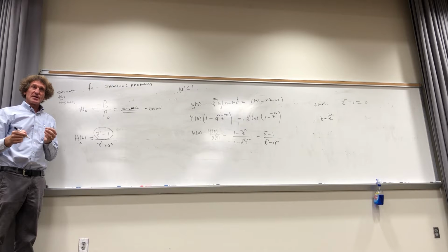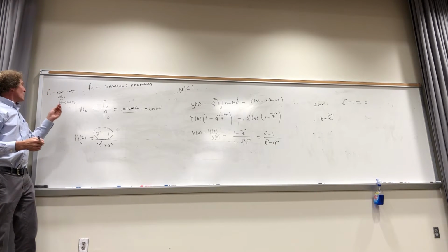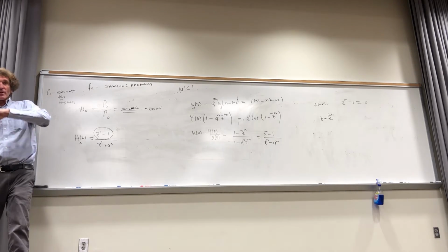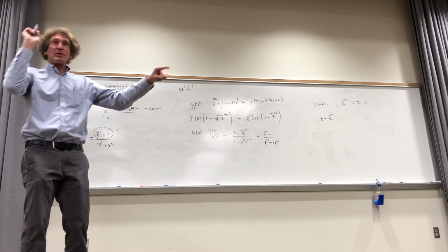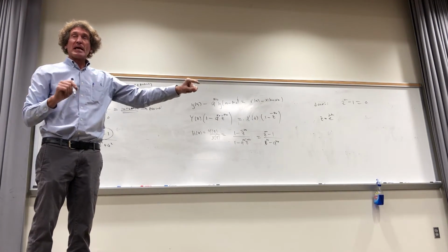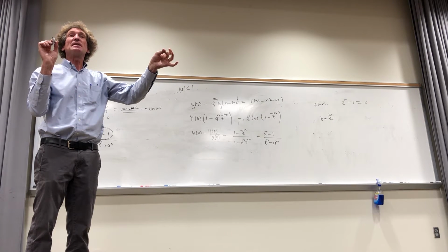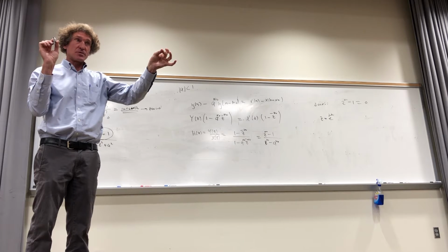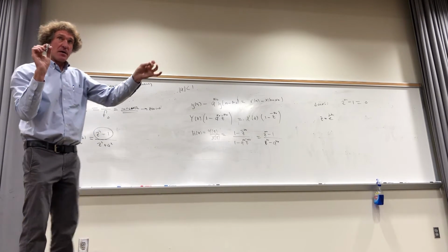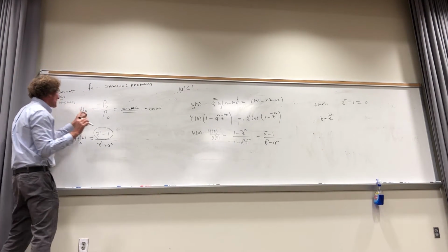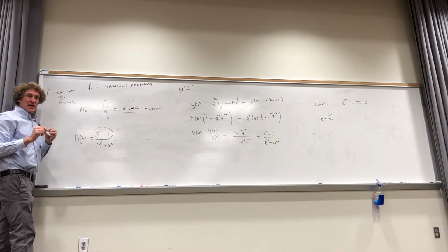If you read the book on this, he goes through it and gives some details of it. But really what you have is a waveform. We have a waveform we want to get rid of f naught. We sample it much faster than f naught, all right? Now, if that sampling is such that there's exactly an even number of samples used to sample that waveform, then we can say that the number of samples would be Fs divided by f naught.